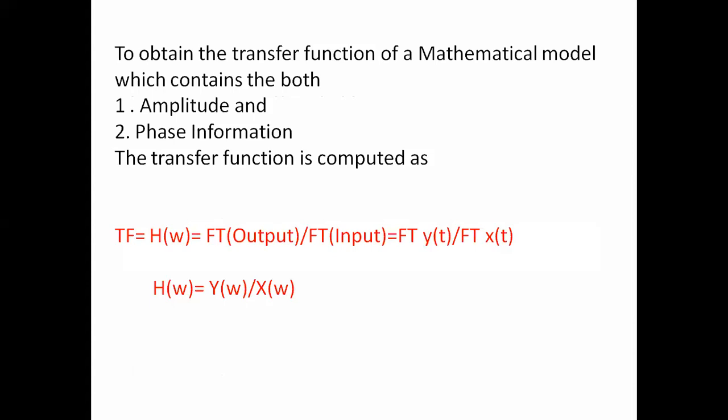Generally, the transfer function is the ratio of the Laplace transform of the output to the Laplace transform of the input. For discrete signals, using this digital signal analyzer, we can perform Fourier transforms: the Fourier transform of the output to the Fourier transform of the input, and with that we can get the transfer function of the mathematical model.